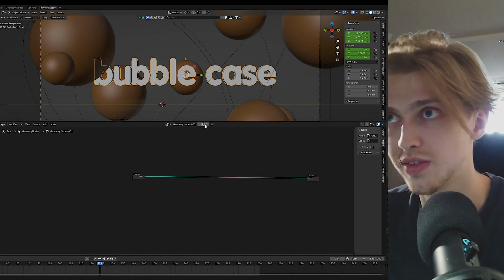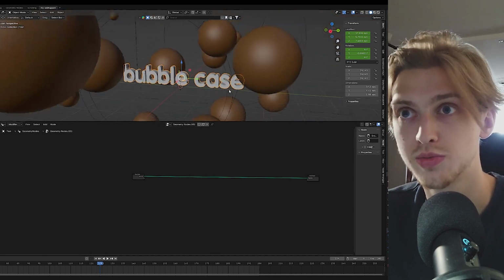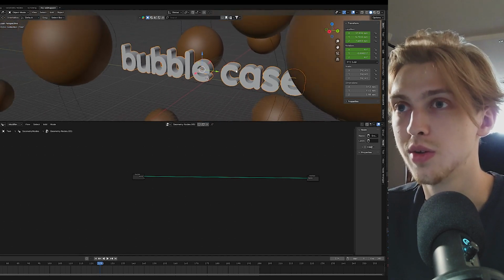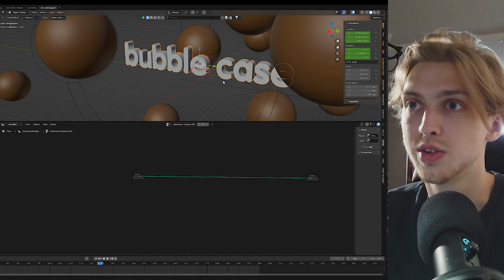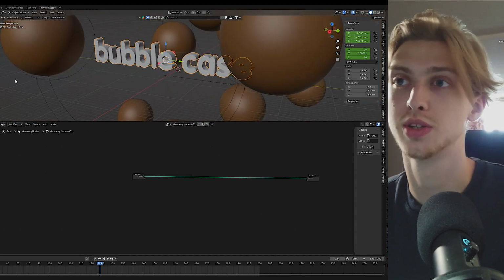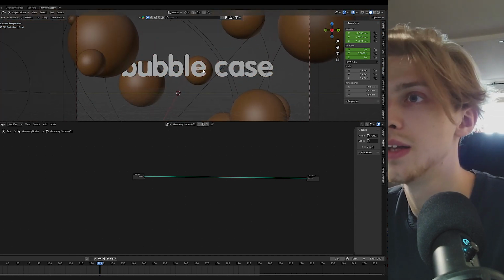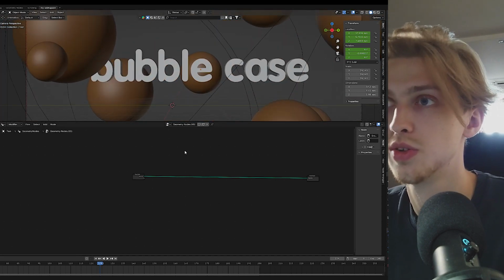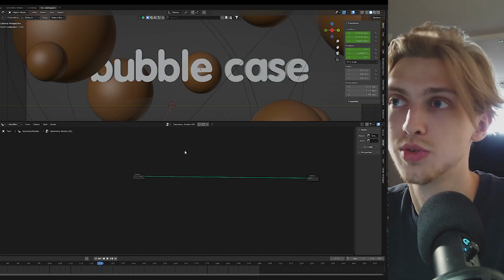Within the text settings, we can immediately extrude it, choose the desired font, and then we convert it into a mesh. Next, we open our favorite geometry nodes and insert the first node called mesh to volume. This means we are converting the entire mesh into a volume. Next, we need to spread the points, the little dots, within this volume. And we add distribute points in volume.